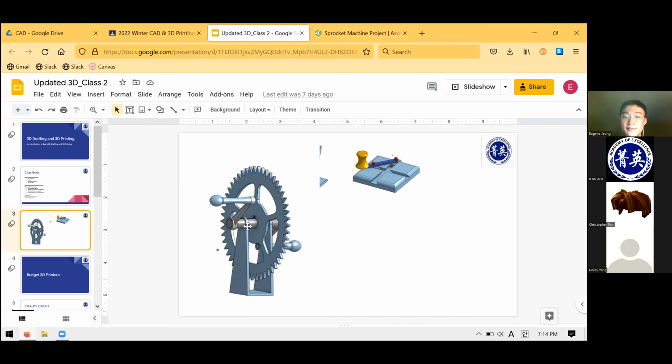With respect to the shaft, how does the link move, or how much freedom does the link have? It needs revolute. So if you did a revolute, what would happen? The link would be able to freely rotate about the shaft. So that means if the shaft were fixed to be perfectly still, I would still be able to crank the handle. And that also means that I can't use the handle to force the shaft to move, because the shaft is allowed to be perfectly still while I move the handle around, right?